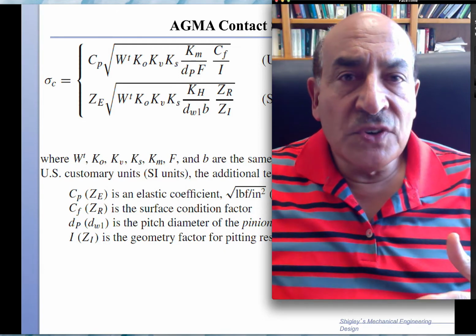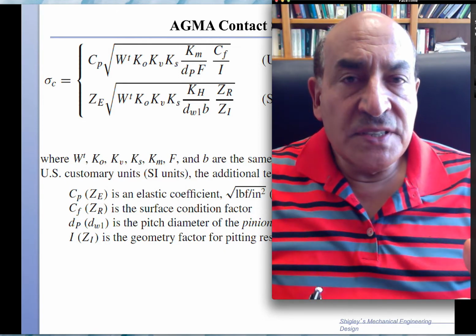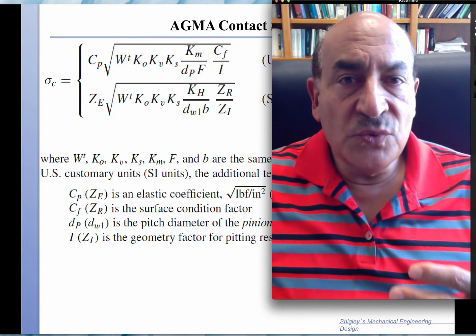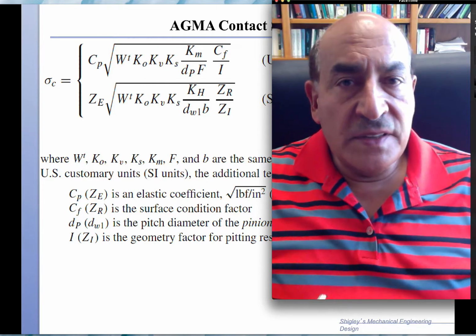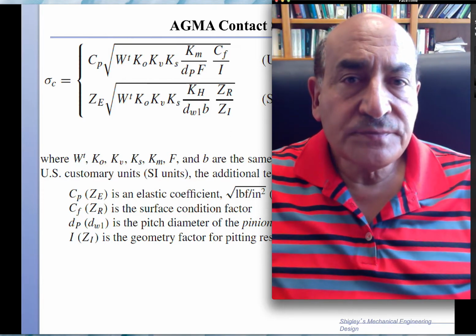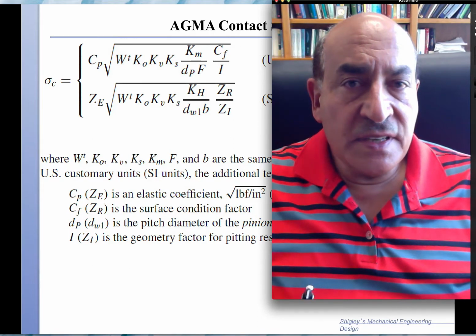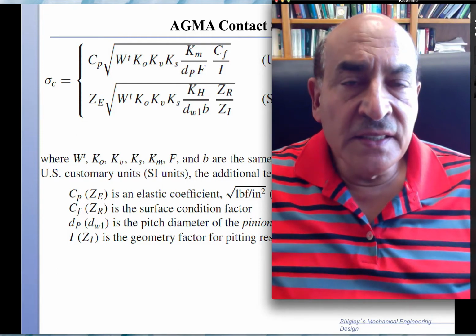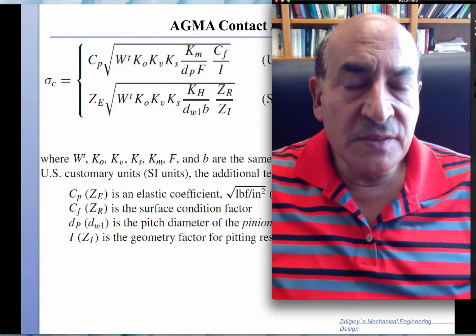We can estimate Hertzian contact stress from knowing the elastic constants of each one of the contacting objects. If they're different, of course, it will be different because we have a pinion and we have a gear. And also, if they have surface effects, like surfaces hardened differently, then we must consider those. That's basically a different type of stress that also must be computed and designed for.